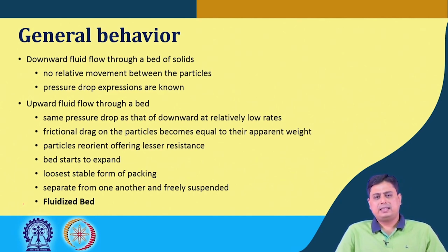Eventually, in a steady state case, when there is a flow downward in a packed bed of particles, there is no relative movement between the particles, and we now know what the pressure drop expressions are and how to calculate those, be it a laminar condition or turbulent condition of the flow region.